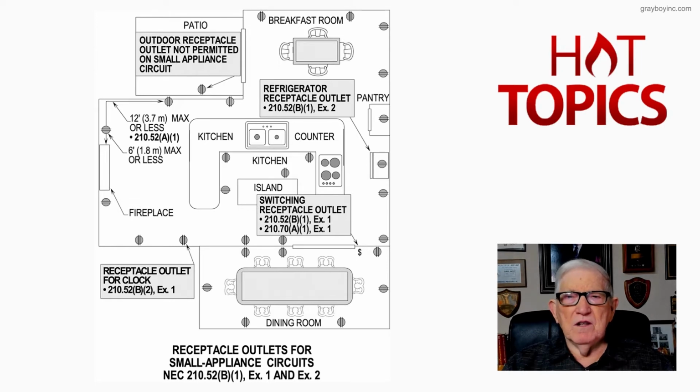Anywhere, say the breakfast room, let's look at that in the illustration. In the center of those two receptacles, you see at the top there, then each way 6 foot, within 6 foot, you need a receptacle. And that's just a good way an electrician can look at that. And a lot of times you'll install those receptacles by just taking the same hammer length and putting it up against the wall and setting your receptacle. Or you put a line across there and set them at 12-inch centers.